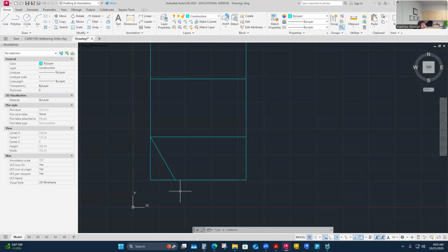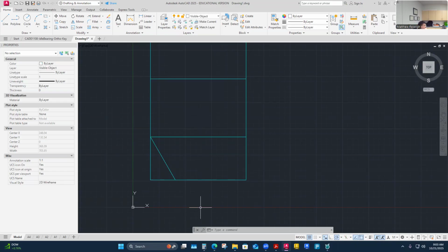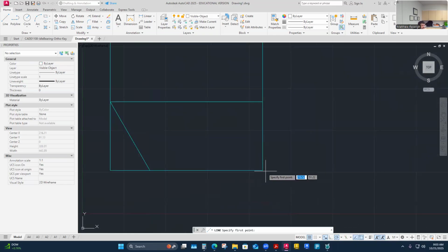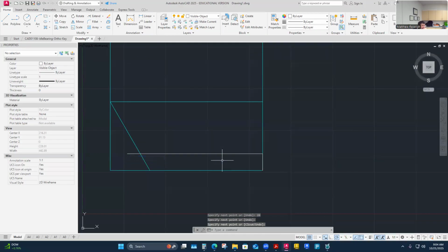So now that I've got that, draw some visible line work here, I think. Maybe I'll just start over here. This is 20 millimeters. I haven't drawn this, and then this one goes across. Maybe I'll just pull it across here. I've got to trim that. It's 20 millimeters through, and then I hit this. This is also 20 millimeters, so I could offset this one.